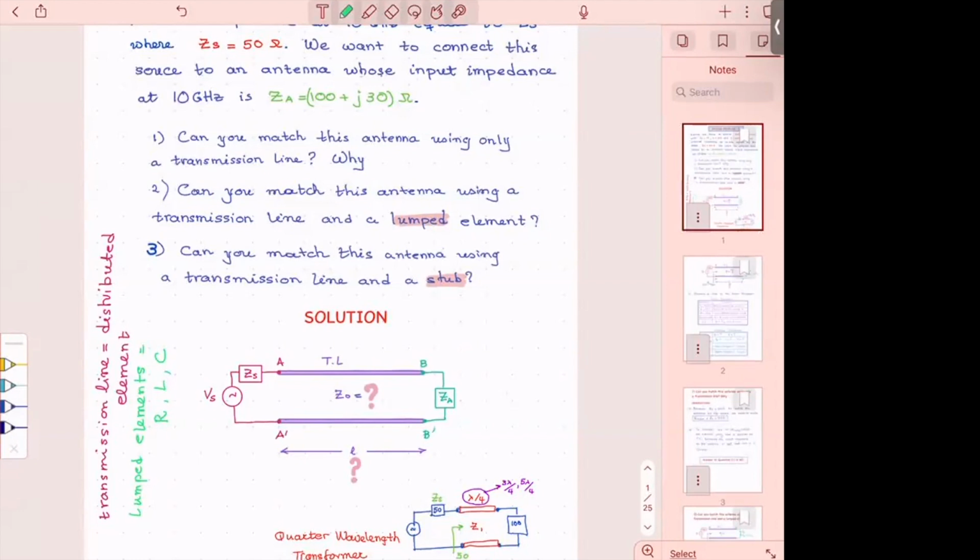But now, our operating frequencies are at that frequency range, and for everything that we do, as a matter of fact, for an iPhone, for everything that we do, unless you go to telescopes that have terahertz frequencies, everything that is an R, L, and C, whether you put it there or you print it, is considered to be so tiny that practically we don't worry about size. And they're called lumped elements, all right?